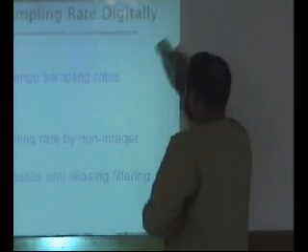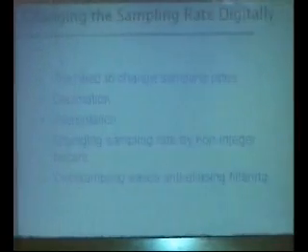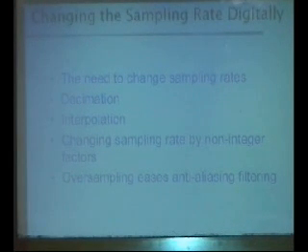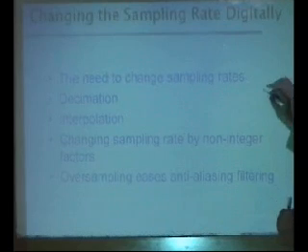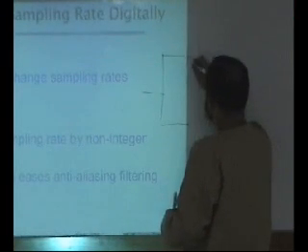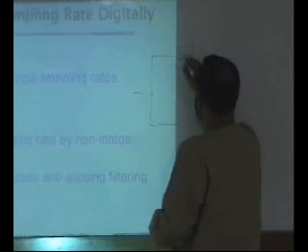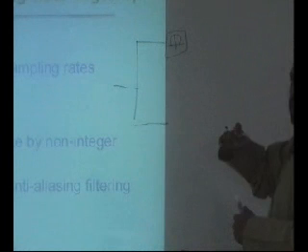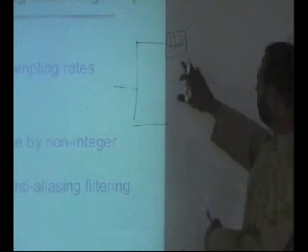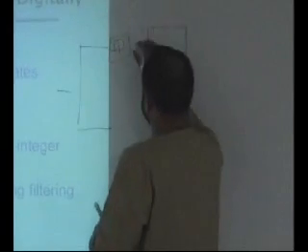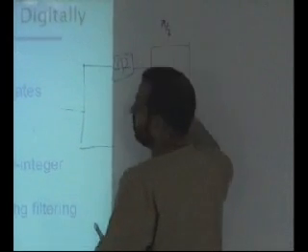Then you bring the signal down. In image processing, there are altogether different reasons for downsampling. In image processing and even in video processing, you have a frame. A frame is first passed through a low pass filter. A low pass filter means you throw away half of the frequencies and you have an image which has no frequency greater than pi by 2.